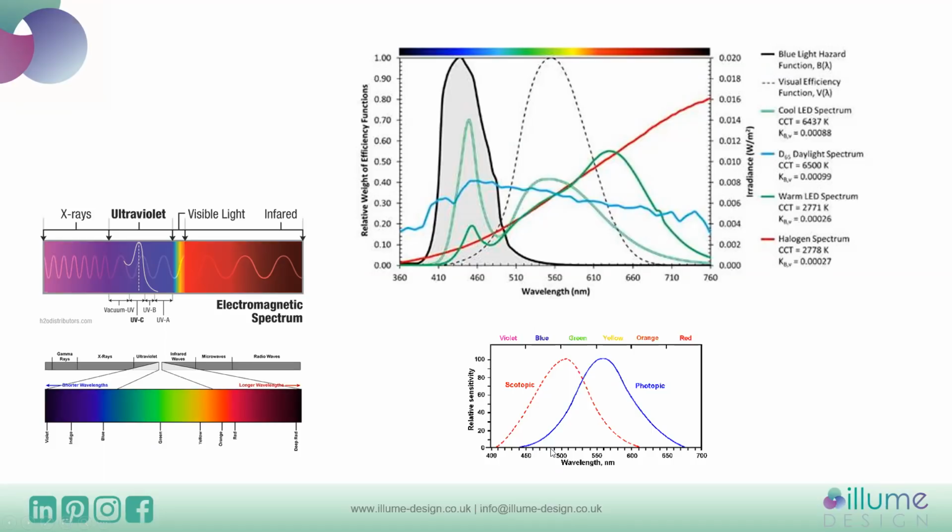And then, our eyesight changes at nighttime. So the photopic is during the day and scotopic is during the night. So that's why when we have blue or whiter LED lights, they appear to be a lot brighter to us, because our eye is more sensitive to those spectrums and sees more effectively in those spectrums. And it's one of the reasons I think that white light was advocated so much in road lighting. Initially, they were using very, very white or cool white temperatures in road lighting.